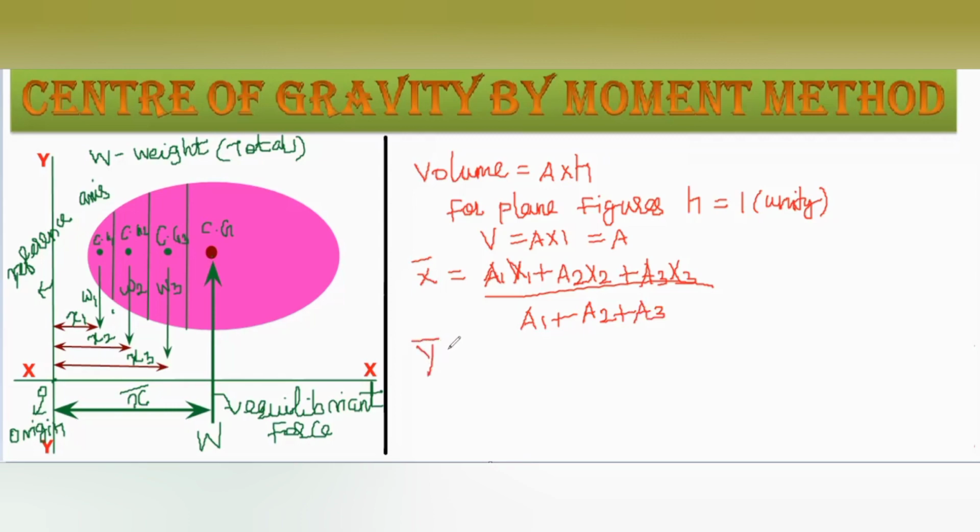Same way, y bar equals a1 y1 plus a2 y2 plus a3 y3 divided by a1 plus a2 plus a3. So these formulas can be used when we have to consider the plane figures, that means for the areas.